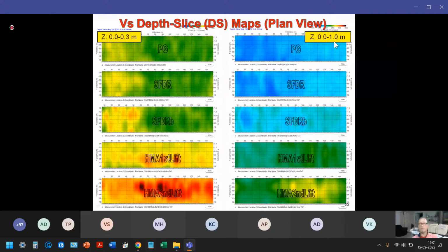And they came up with the results at 5 different stages of that road construction. And we can see the shear wave velocities are gradually increasing during the first 3 stages, and then they increase very rapidly for the last 2 construction or compaction stages.